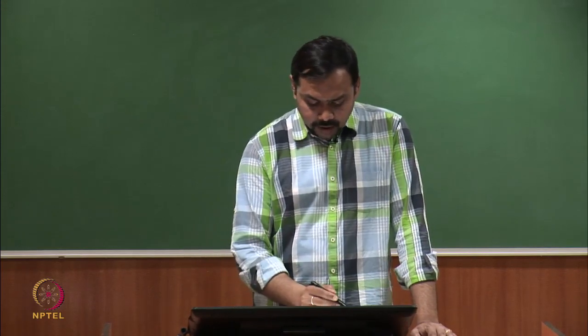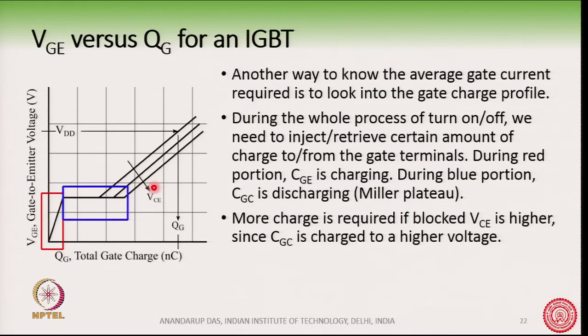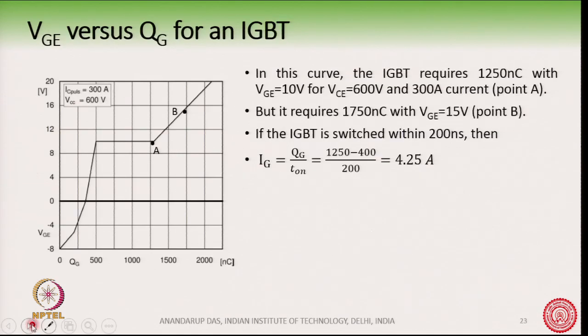Therefore, as VCE or the DC bus voltage increases, we will require more charge in order to fully turn on the device.